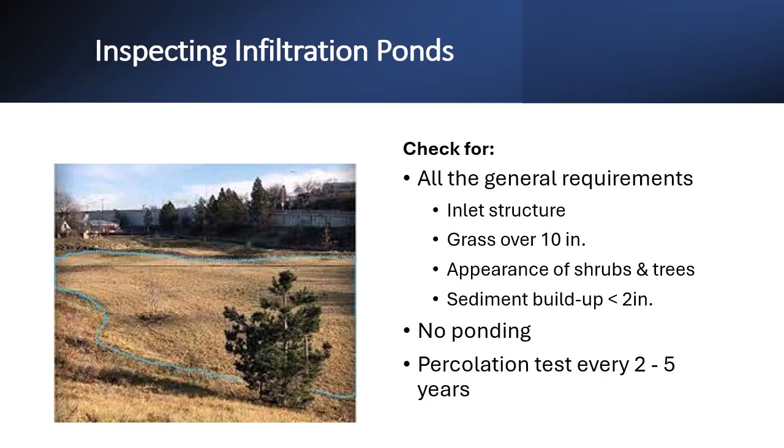Again, there should be no more than 2 inches of sediment buildup, and there should be no ponding or standing water 72 hours after a storm. If ponding becomes an issue, excessive growth of water-loving plants such as cattails may start to appear.